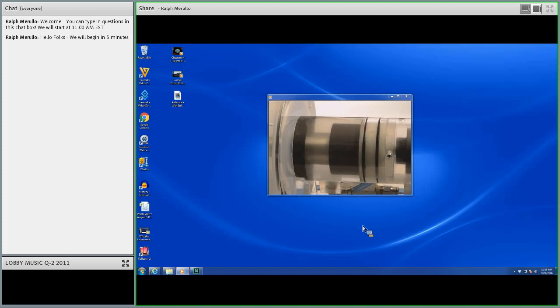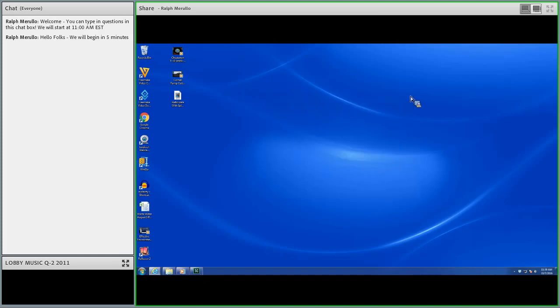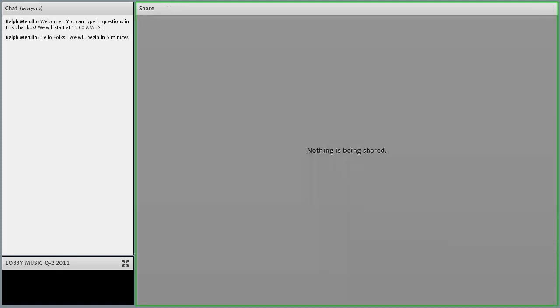This particular device also has a groove mounted at the 12 o'clock position for horizontal shafted pumps that allows air to escape. So the seal is completely immersed in fluid. The problem is, in a conventional pump, air gets trapped, so the seal is actually running in a mixture of air and fluid, and that causes issues. If you immerse the seal completely in fluid, like the lubricated face seal, it works much better. So that's an example of what that is. Let me stop sharing here. Back to here.